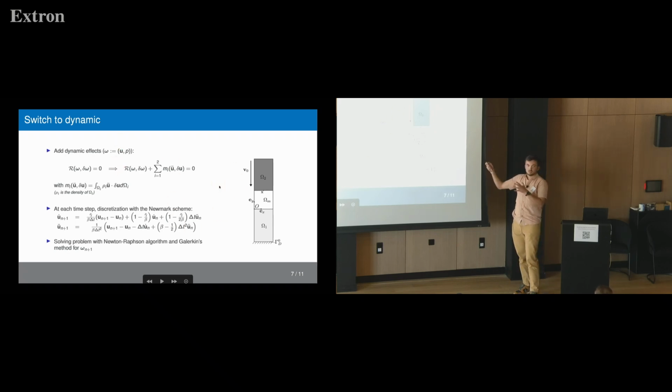We are still working with a 3-body system, but this time we are working in 2D. And I changed a bit my boundary conditions. On the two sides, we've got a blocked horizontal displacement. We still have a clamped displacement at the bottom, but we changed the condition on top: we don't have any prescribed displacement anymore, and we changed it for an initial velocity on the whole body.